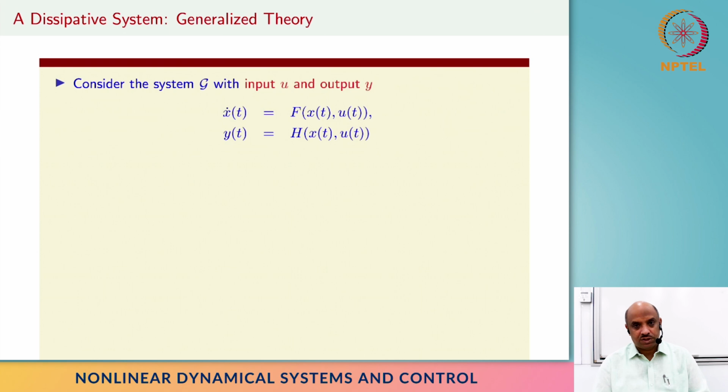And then this question was considered by the inventors of this dissipativity theory, and the answer seems to be quite interesting. Just like the converse theorem for Lyapunov functions, which said basically if you have an asymptotically stable system, we can actually construct the Lyapunov function through some magic, through these class K functions and things like that, quite a complex kind of functions.